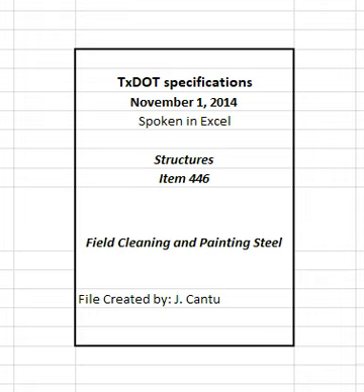When the plans specify the existing coating to be removed contains hazardous materials and steel grit is used as the abrasive, the waste generated is classified as hazardous or universal waste regardless of the results of the TCLP.